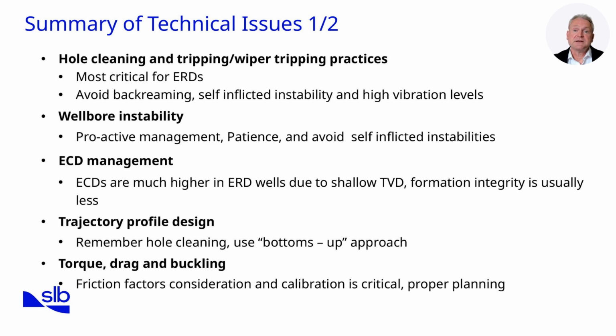Trajectory profile design plays a role too. A bottoms-up approach, with cleaning in mind, is more effective than chasing the shortest possible well path. Torque, drag, and buckling are constant challenges, and the calibration of friction factors through real-time data is critical for effective planning. The next set of issues builds on these themes, particularly around BHA and survey design.